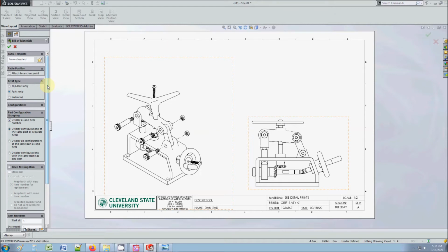You insert sub-assemblies in a master assembly. Like when I design a machine, I insert a sub-assembly of the electrical panel, a sub-assembly of the hydraulics. Okay, so when you create this bill of material, you have the option to either display all the nested parts in the sub-assemblies or display just the sub-assembly name. So I highly encourage you to just stick to the top level only.